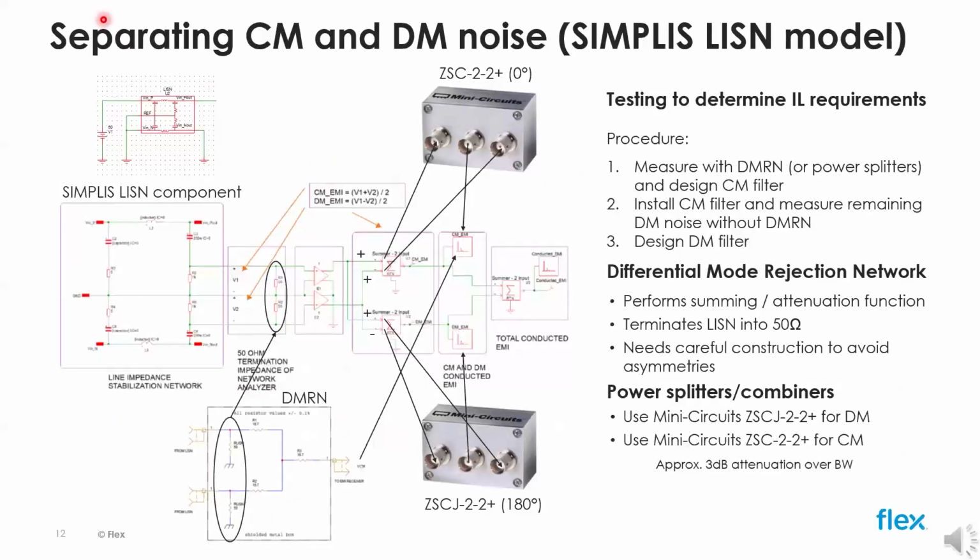We design our EMI filter by mode separation. In other words, the common mode and differential mode filter circuits are different. The 2 modes typically also have different insertion loss requirements depending on frequency ranges. To determine those requirements, we need to know the actual contribution of the 2 different noise modes.